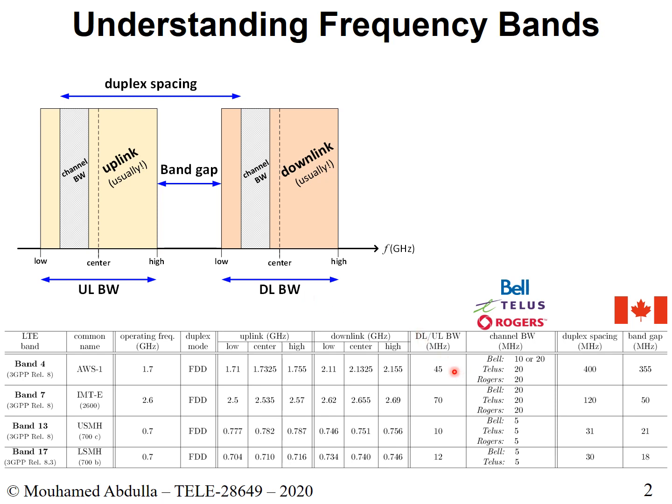That's the downlink and uplink bandwidth. The other thing that is important to know is that anytime you use your phone, you will not be given the entire bandwidth for downlink and uplink. This might be shared with other people that are using this frequency or this band, operating with one of your carriers. So you will only get a slice of it. The slice that you use is referred to as a channel bandwidth.